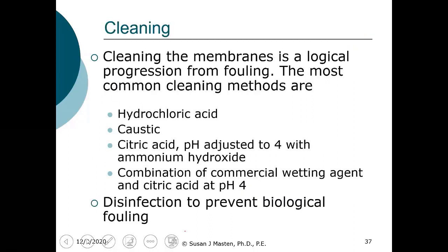And then finally, I mentioned cleaning. Fouling will occur. It's almost inevitable. Once the fouling occurs, you need to clean the membrane, and that is typically done with acids or bases, or in some cases, a combination of both. And then you also may, again, disinfect to prevent biological fouling.